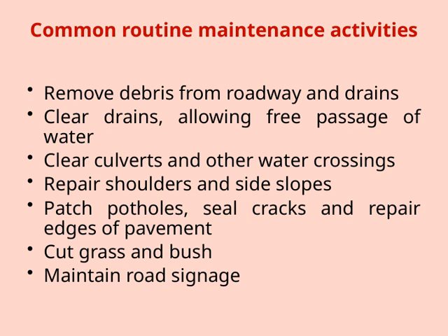Patching potholes, sealing cracks, and repairing the edges of pavement are ongoing tasks that extend the life of the roadway and provide a smoother, safer surface for drivers. Additionally, cutting grass and bushes along the roadside improves visibility and safety. Maintaining road signage is equally important because clear, visible signs guide drivers and reduce accidents. All these activities, when performed regularly, contribute to the overall safety, durability, and functionality of our roads, making sure they serve the community effectively and efficiently.